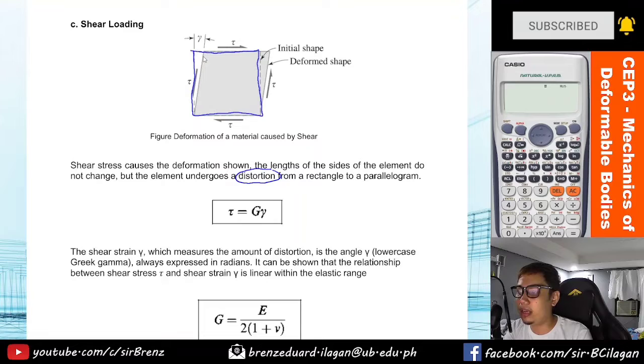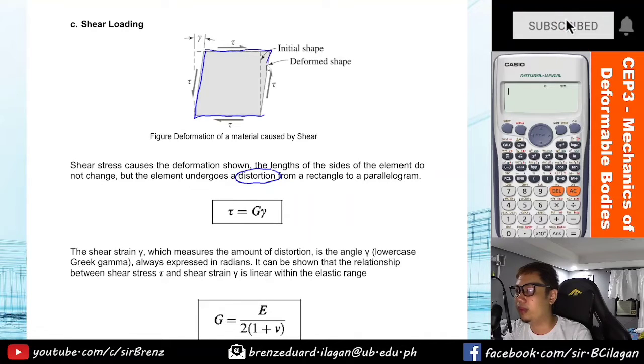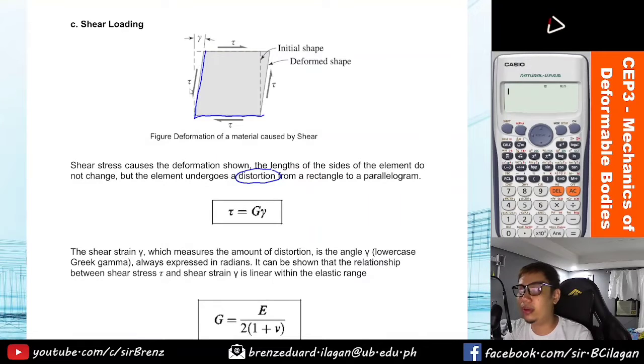When the forces are applied, it undergoes shear deformation, and you can see it distorts. This is different from torsion. This happens because of the shearing, and coming from a square or a rectangle, it became a parallelogram.